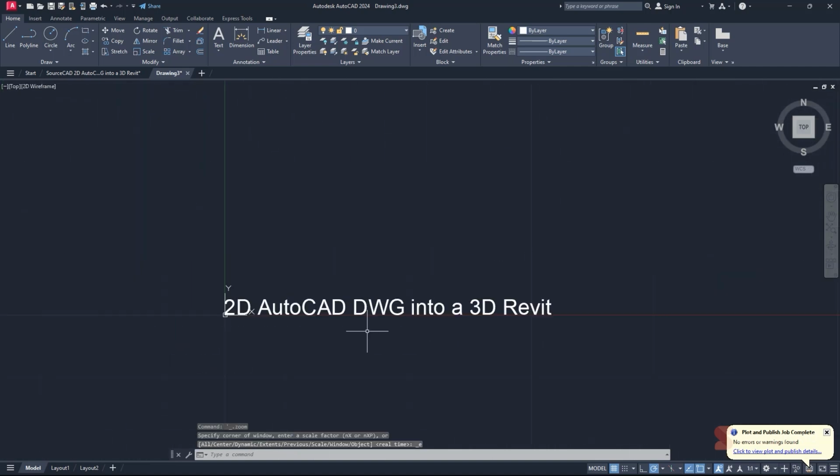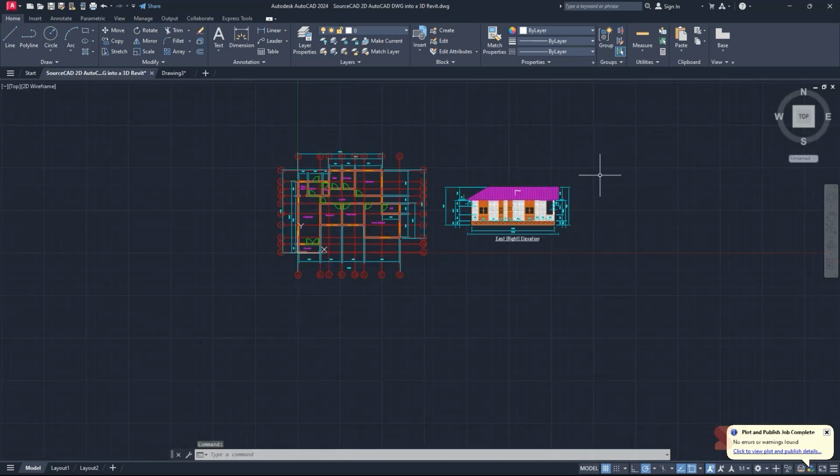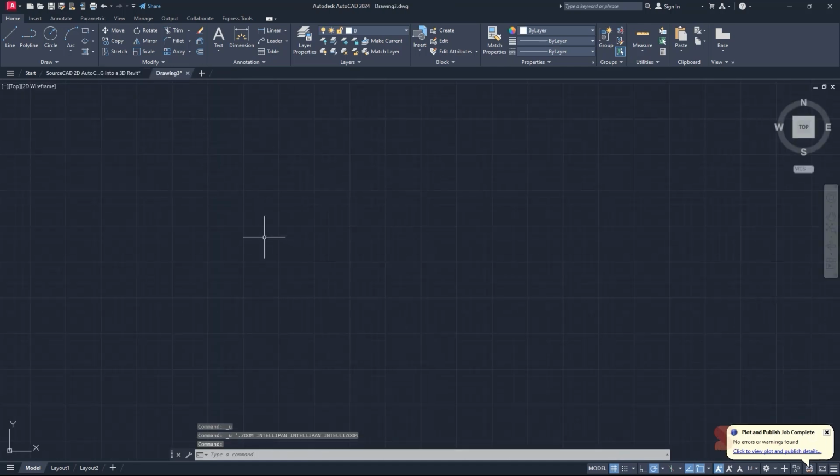And then I'll just simply double click. Then once that's done, I'll simply go back to my main drawing here. I'll select what I have here, then Control X because I want to cut it, then move to this other drawing, then Control V. So you can also use the paste options that we have here, but just Control V will also do. Specify the insertion point 0,